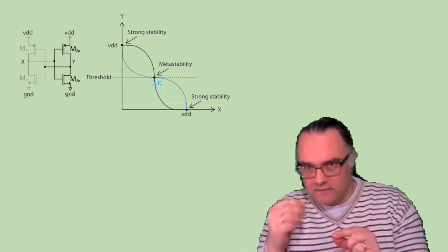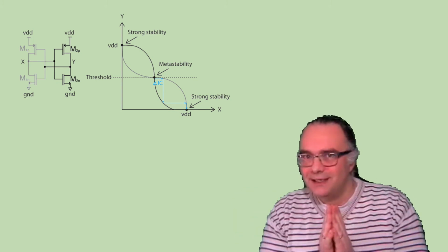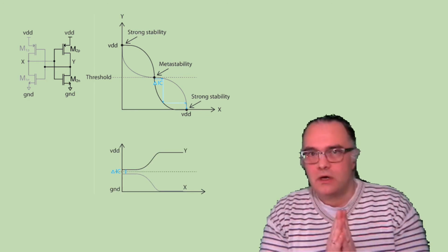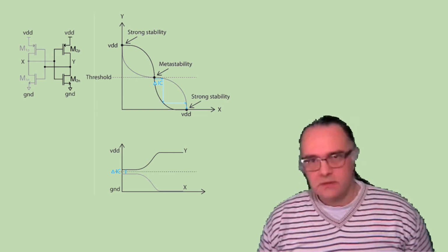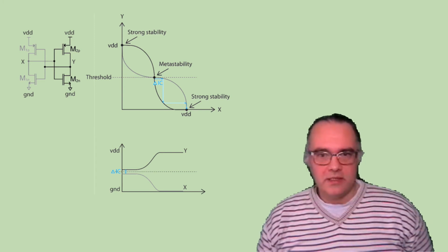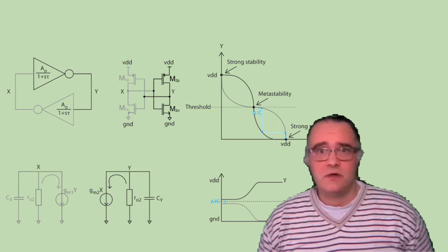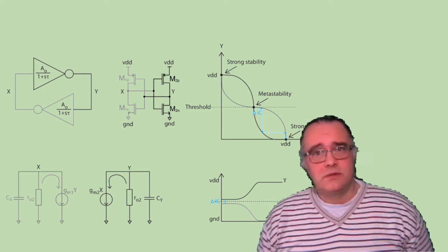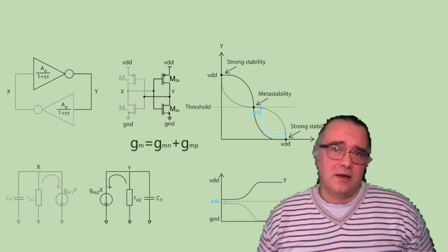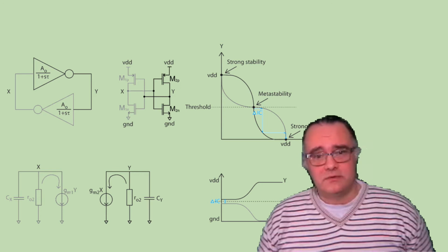And we will investigate what is exactly the analytical function that governs the settling and what it depends on in terms of circuit parameters. Because ultimately this will determine the time and gain of the comparator. Now, how can we analyze this circuit? For the model of the inverter, we'll use a single pole amplifier, which models the two transistors with an equivalent GM, transconductance stage. This is a voltage dependent signal source.